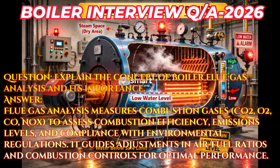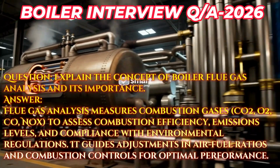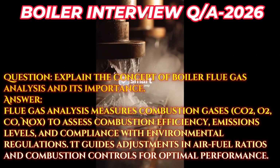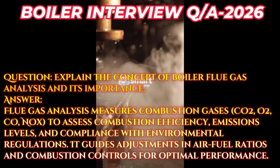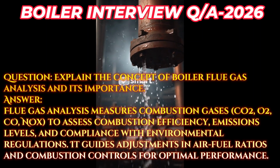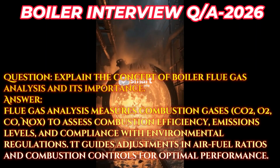Question. Explain the concept of boiler flue gas analysis and its importance. Answer. Flue gas analysis measures combustion gases, CO2, O2, CO, NOx, to assess combustion efficiency, emissions levels, and compliance with environmental regulations. It guides adjustments in air-fuel ratios and combustion controls for optimal performance.